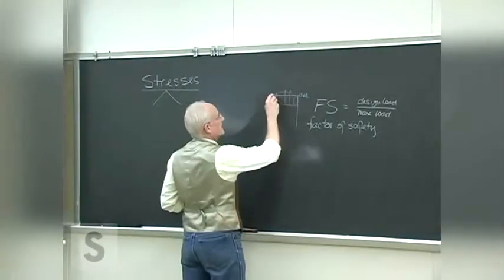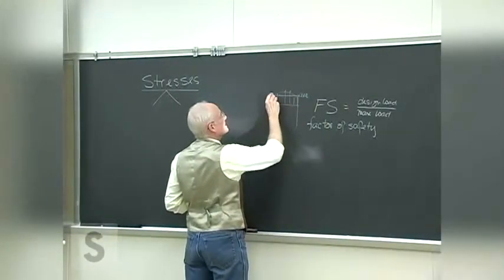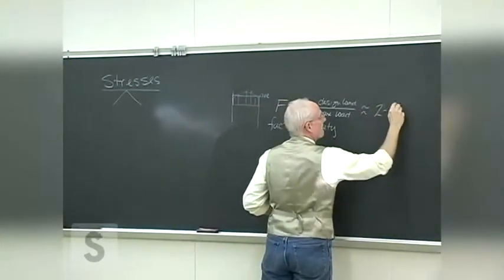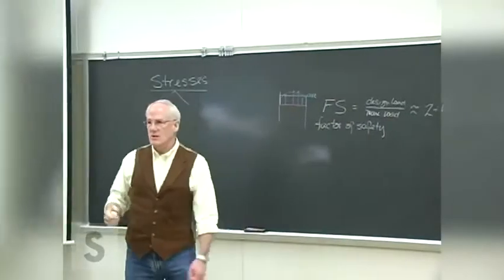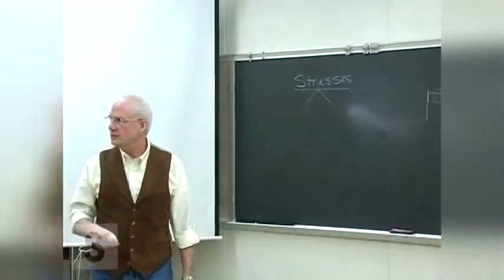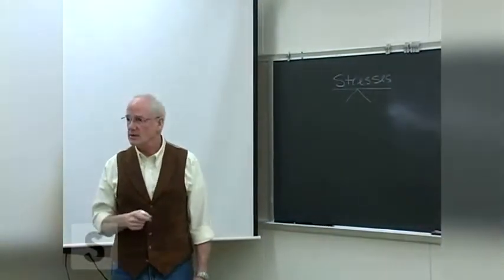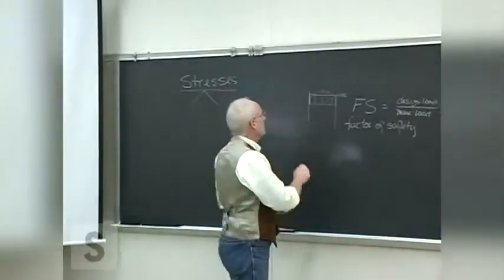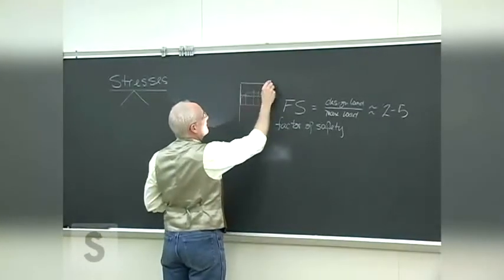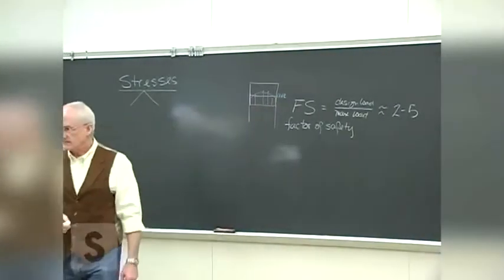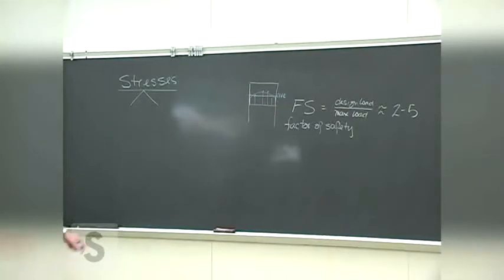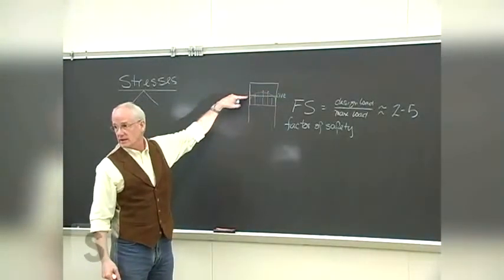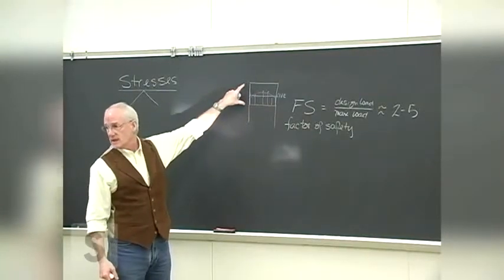So if we're calculating for these average stresses, we apply a factor of safety, which can be somewhere on the order of 2, 3, 4, 5, depending upon what the application is, where you figure out what the maximum load is, and then you simply design for twice that. So you're well over the maximum that we were missing because we were averaging. So we eliminate the concern.